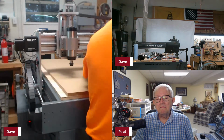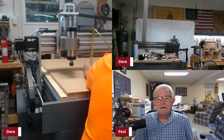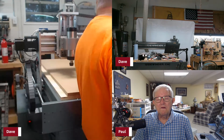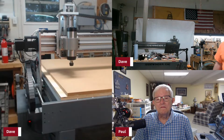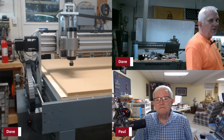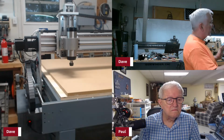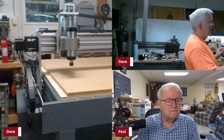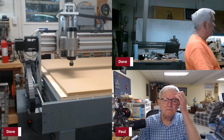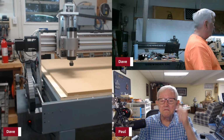Right now it's got right at 6 inches of clearance under the bottom of here. I had 8 inches clearance with my Avid, and I never even came close to using half of that with stuff I put on there. So I decided I'd rather get it lower. The lower you can get it, the more sturdy it's going to be, because the higher up you get it, you got more stuff to flex.